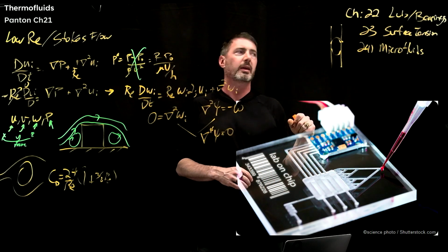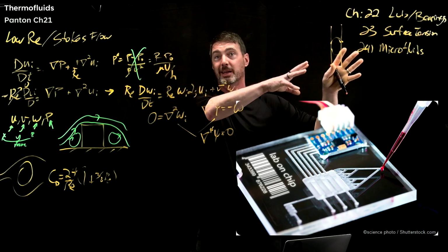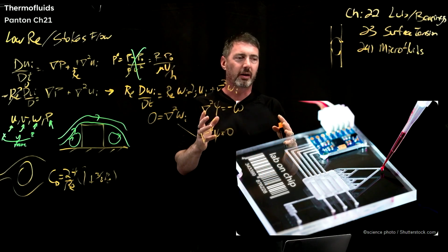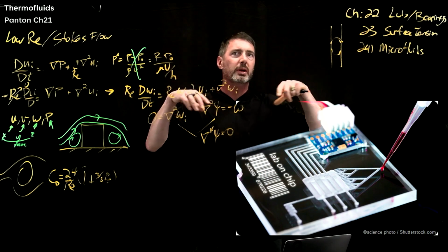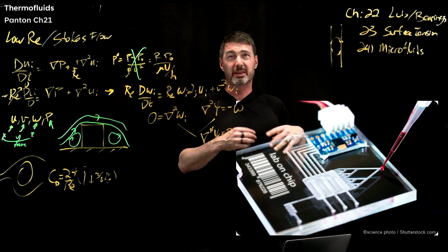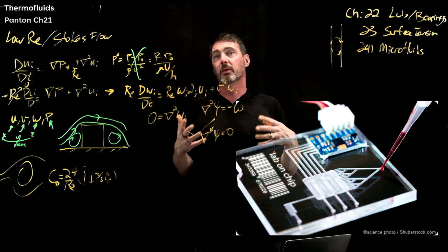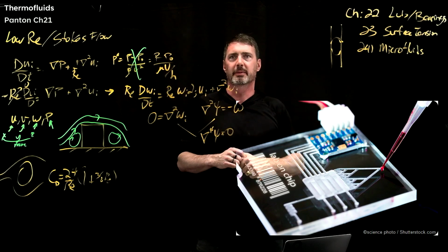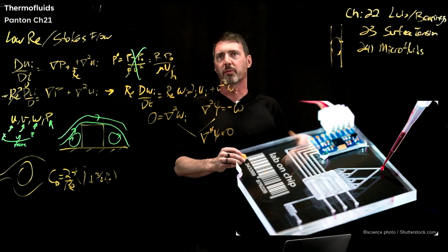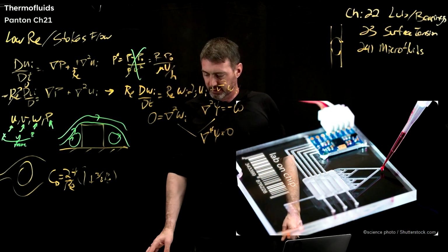Basically, the punchline of microfluidics is that it's Stokes flow and it's surface tension driven, and our intuition in fluid mechanics is wrong in these devices. We're used to air, which is a higher Reynolds number, and water, which is still even higher, so our brain's sense of how fluid mechanics works is very different, very wrong in this molasses world. It's a good introduction.